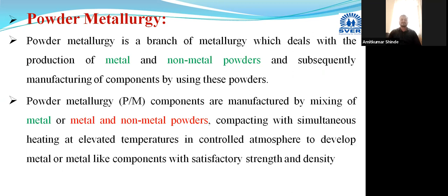The first step is powder production, then mixing or blending, the third stage compacting, then sintering, then sizing or coining, and last is testing and inspection.